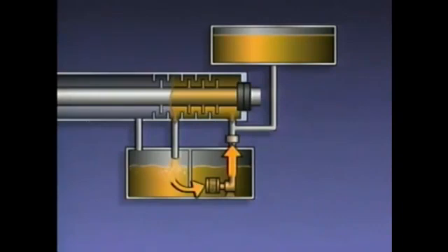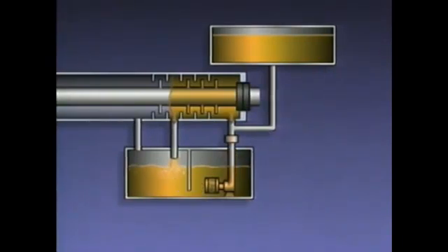The oil flows to the oil pump and is then returned to the head tank. The head tank is used to supply oil to the seal if the pump fails. The check valve keeps the oil from the head tank from flowing down into the oil pump and forces it to flow through the seal. The head tank contains enough oil to allow the compressor to be shut down without a gas leak if the seal oil pump fails. The next components we'll look at are bearings.